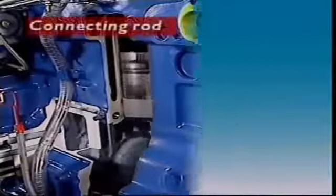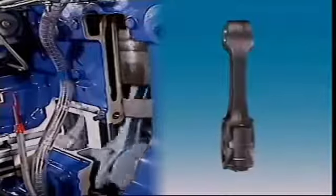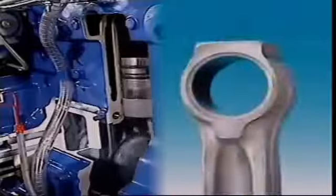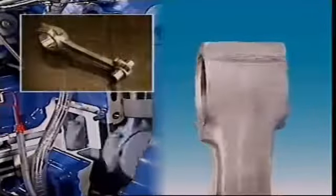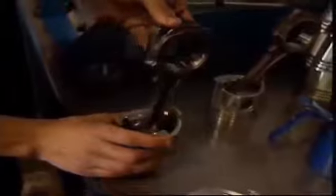This section examines the connecting rod. The connecting rod connects the piston to the crankshaft. It's fastened to the piston at its little end by a piston pin, also known as a gudgeon pin. In some engines, the pin is a press fit in the small end of the connecting rod.